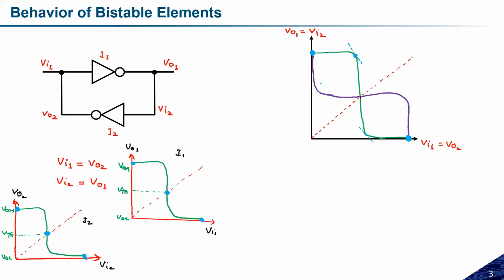But if you see here, this is the point where both the inverters are touching the input one, like they are crossing, and at this point both the transistors in a particular inverter will be in the saturation region. Now if you consider this point and both the VTC characteristics of both the inverters, this is the point where all four transistors are in the saturation region.